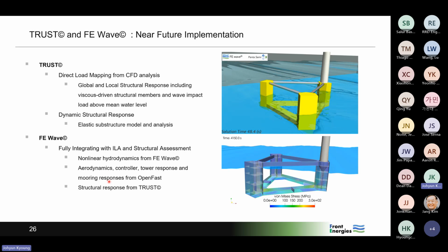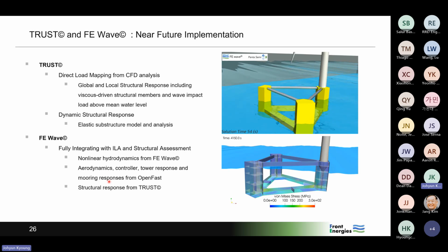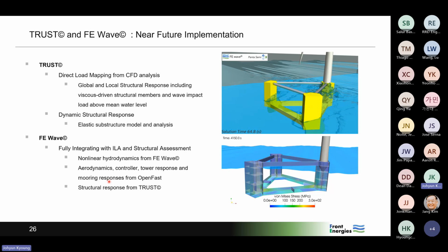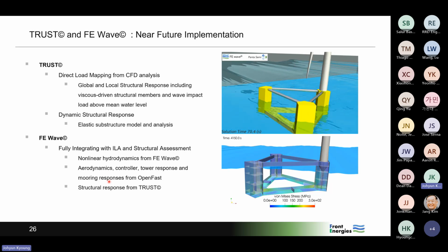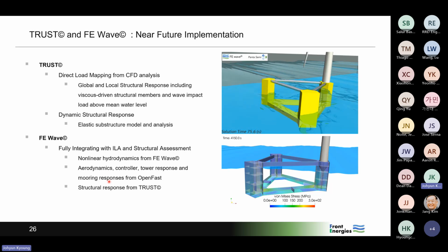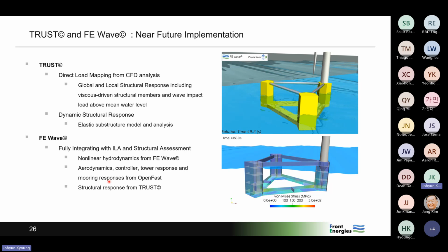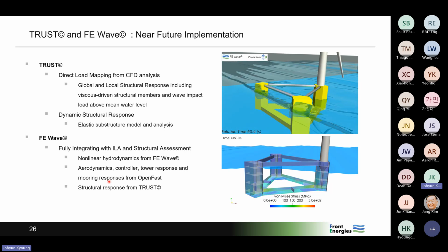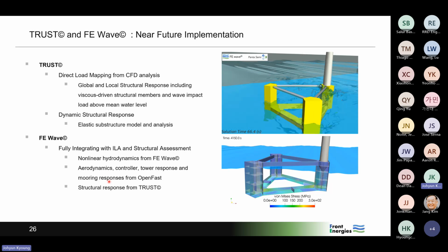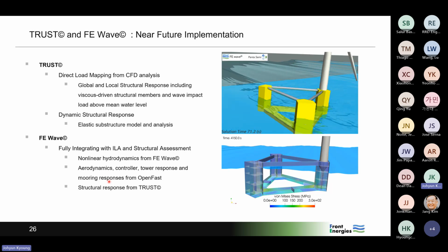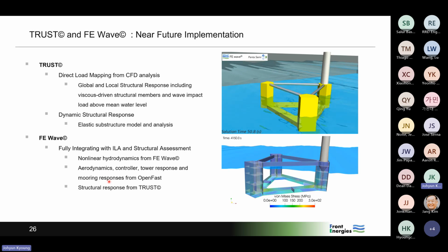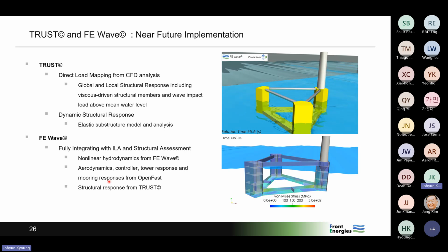But inertial loading, I mean, the acceleration coming from OpenFAST, you apply them directly in your finite element model. Right. But the pressure loading, you have some interpolation and something. So you will have something to adjust to be balanced, if you see what I mean. Interpolation, but we use the same WAMIT, same panel for the. I understand. Right. Okay.